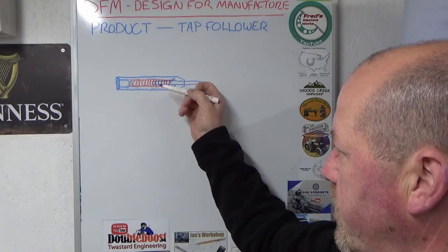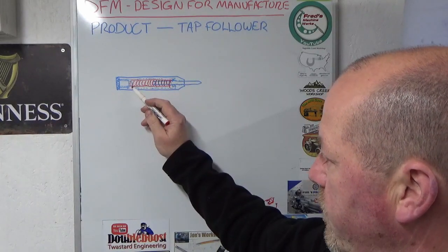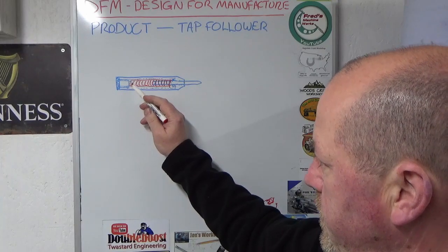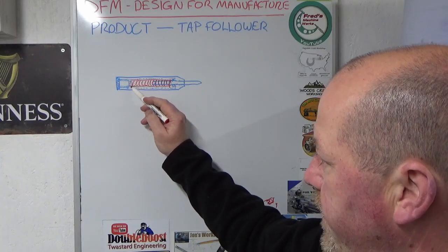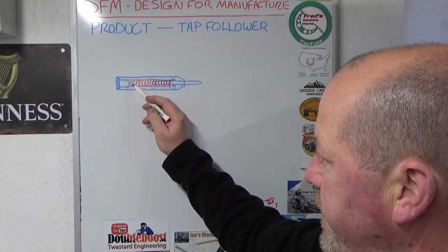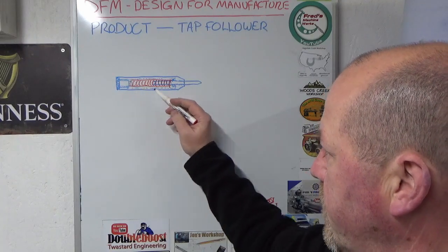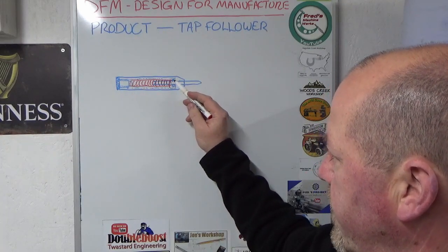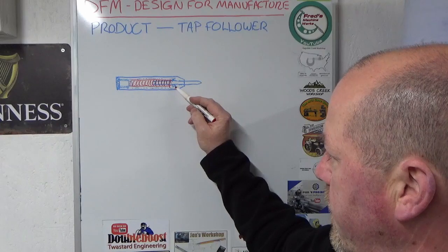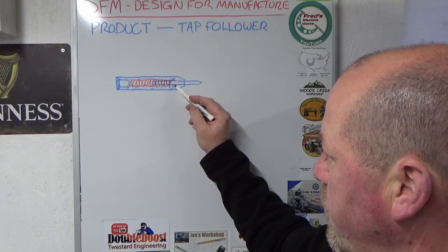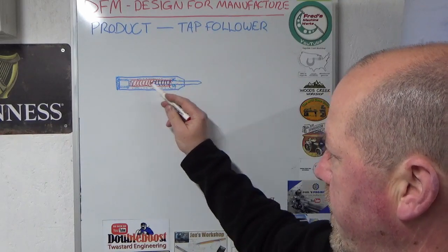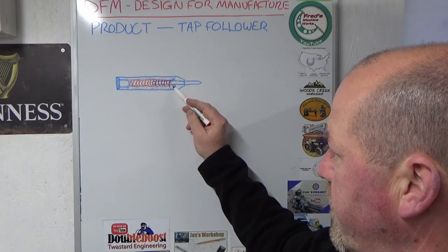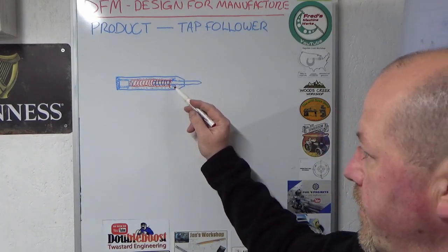from tipping this way. I've drawn roughly a bung on the end of the threaded plug at this end to locate in the inside diameter of the spring, and obviously this shoulder here that I've just spoken about serves two purposes. One is the location, and two, it serves as a face for the spring to put up to.